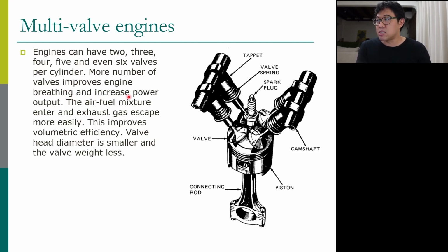When you provide more area, the engine needs less power to suck in the air, because you have a lot of opening. It uses less power to intake the air, which means the engine can produce more power, since it can give that back to drive the car. So that increases power output.